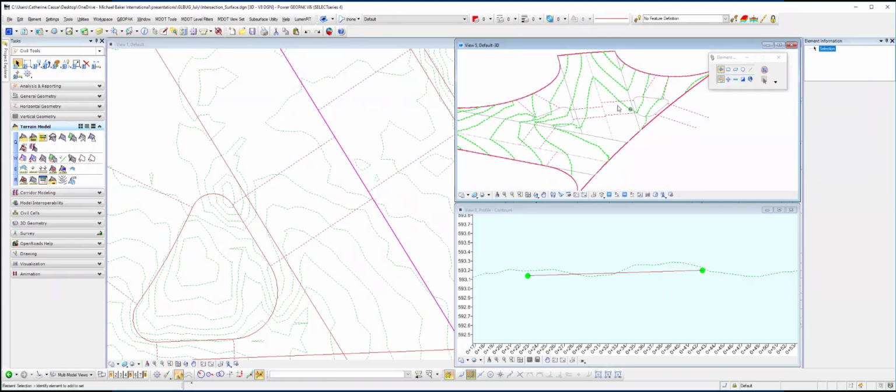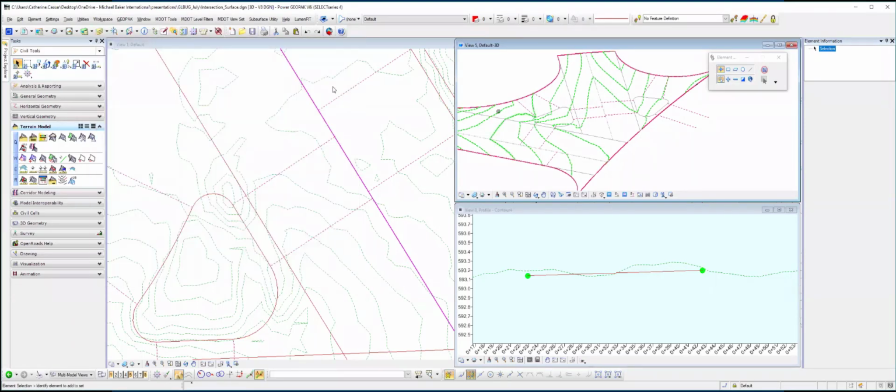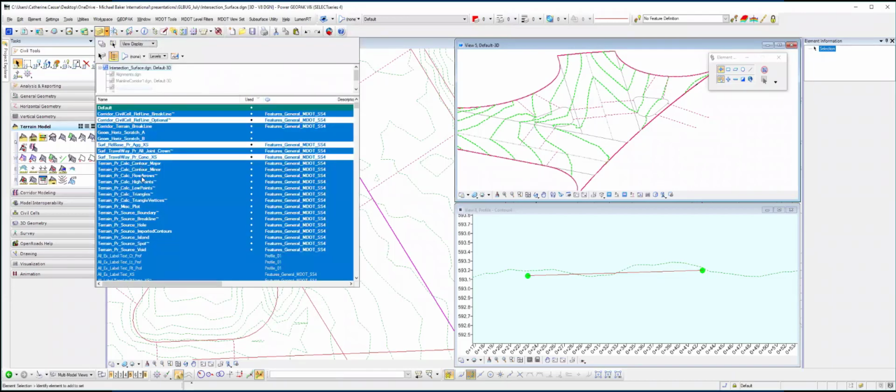The boundary element, no, it is not exactly dynamic. So once you create it the first time and you have that boundary, it's a static item. It's not linked to the model. It's part of it. Otherwise, you end up with a circular referencing. So the boundary is something that you have to kind of continually manipulate. Unfortunately, that can get a little bit frustrating when you want to work with it.